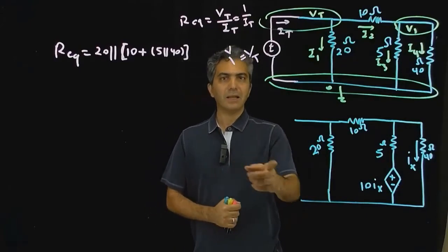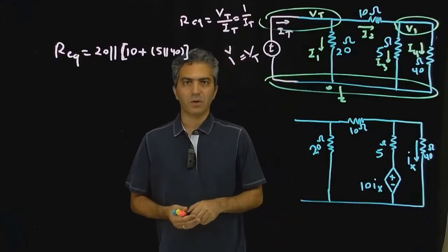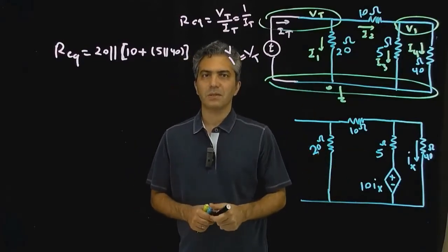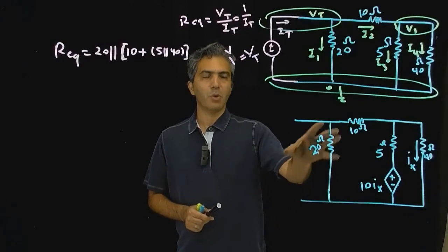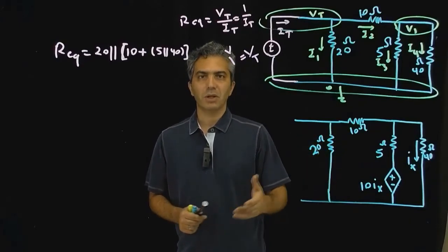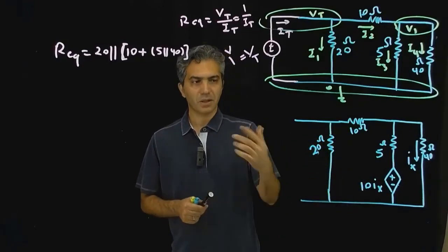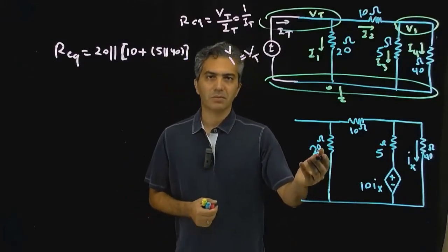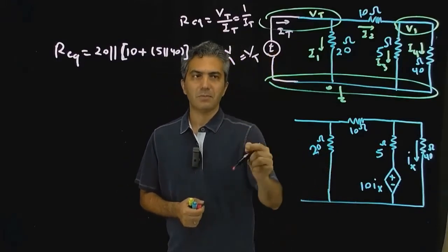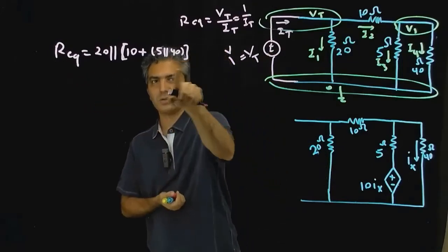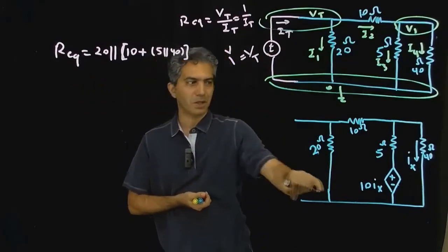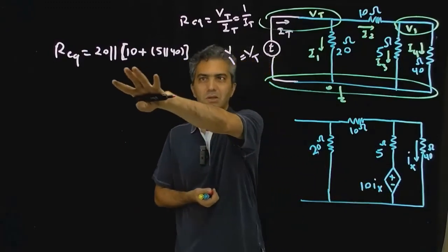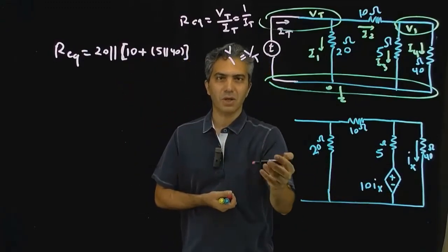So what's again left, like what we saw before, is that the equivalent resistance is the only portion of the Thevenin or Norton model that could be calculated for this circuit. The other part is 0. Now, again, how do we do equivalent resistors? Exactly the same thing. This time you can't actually use that shortcut, because of this source being here, none of what we used here is true anymore.